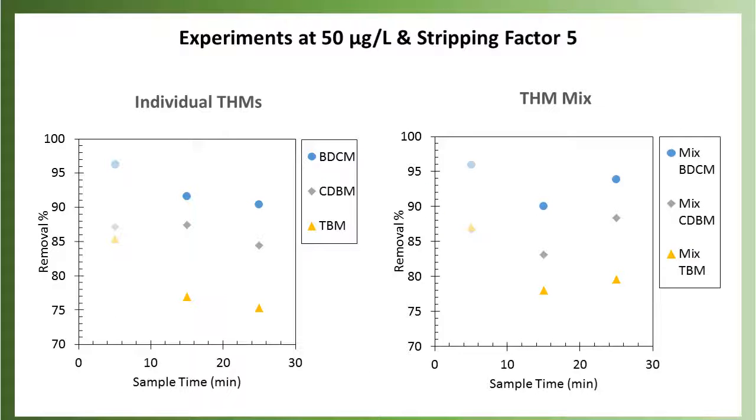Yes? So you're just running a continuous flow, and does it come to equilibrium over time? It looks like it's changing a little bit over time. Yes. So at the 5-minute increment, we actually determined that it may not quite be at steady state yet. However, after that point, it looks like it had approximately reached a steady state value. The reason why it was reaching a steady state later is because it has to form the liquid gas interface within the membrane. Okay. And so that takes time. And so that's why you see a little bit of decrease over the beginning. But then once it's reached steady state, it's approximately constant.